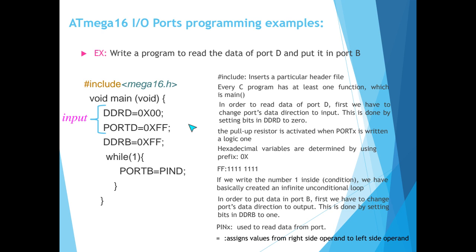Yes. If we want to write the number in terms of binary numbers, meaning that by using 0b here, we should write, instead of each of the f's, 4 ones. Because each of these registers, as I explained in the previous session, includes 8 bits. Anyway, it's better that you review the previous session to understand the programs in this session more.